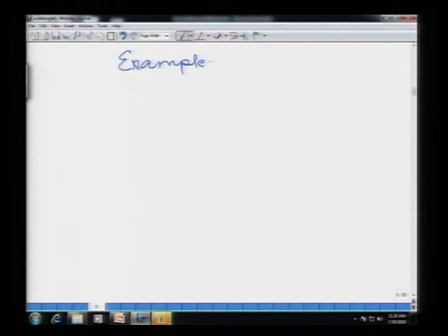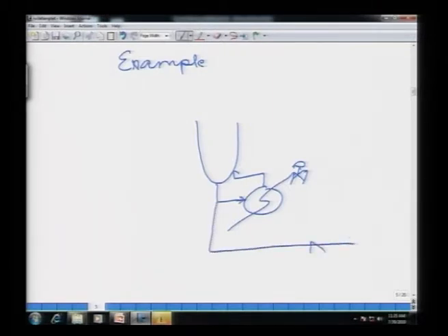Consider a distillation column. So, you got a distillation column, you got the reboiler where you are putting in steam, the liquid in the reboiler boils and this reboil is sent back into the column, and of course, some of the liquid is drawn out, and in the column there are trays. Okay. There are trays in the column and down comers. So, there is liquid on this tray which is actually flowing down and collecting in the bottom sump. This is the bottom sump.